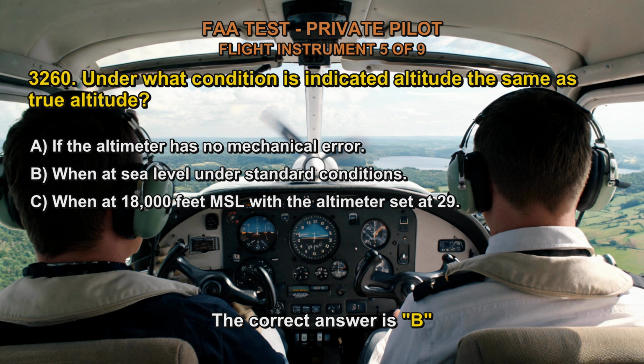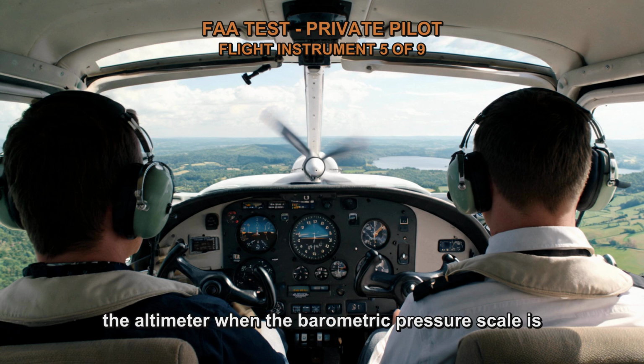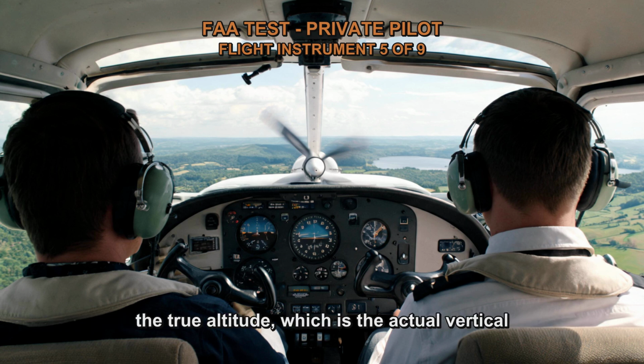The correct answer is B. Indicated altitude is the altitude read directly from the altimeter when the barometric pressure scale is set to the local altimeter setting. It represents the height above the surface of the Earth. However, indicated altitude does not necessarily correspond to the true altitude, which is the actual vertical distance above sea level.